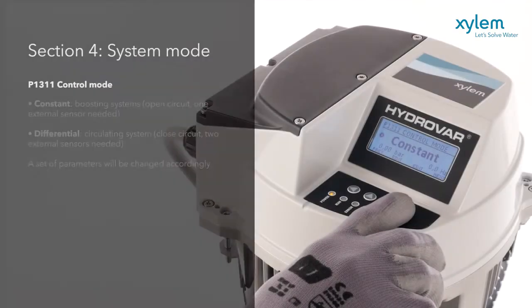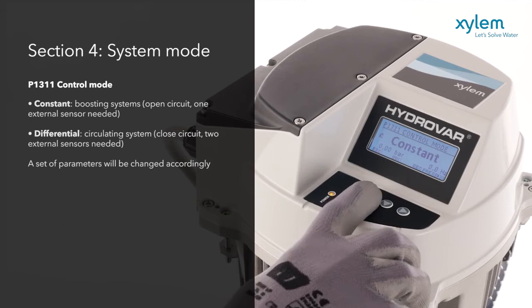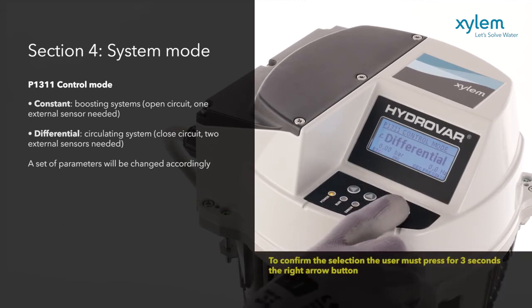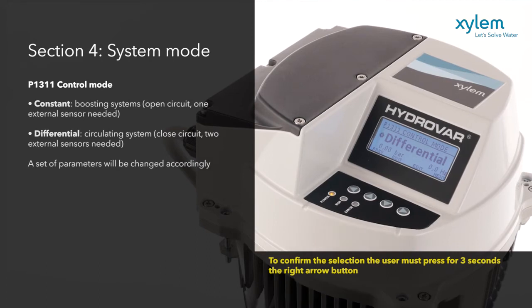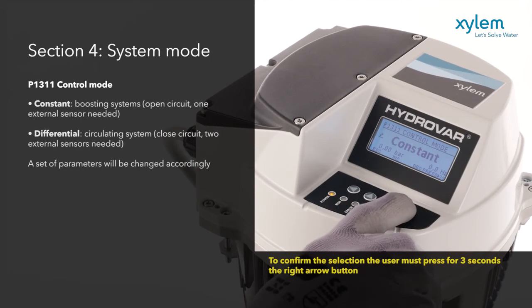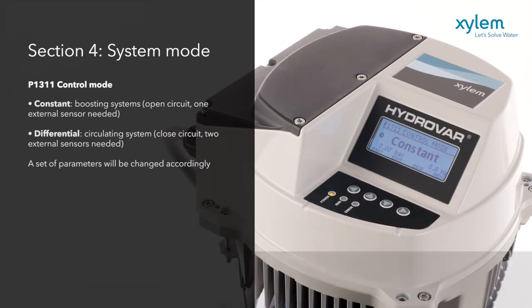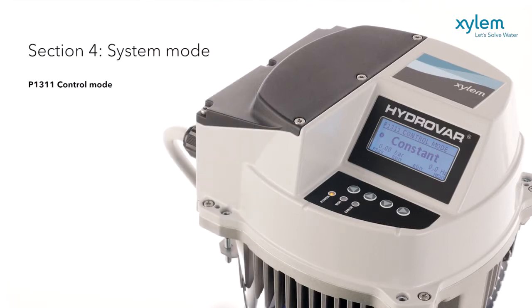In control mode, you can choose between constant for constant pressure systems or differential for closed loop systems. The parameters change on screen accordingly. Remember that constant pressure requires 1 pressure transducer, while differential pressure requires 2 pressure transducers. There are other options. Follow a system curve and control the pump according to an external signal.